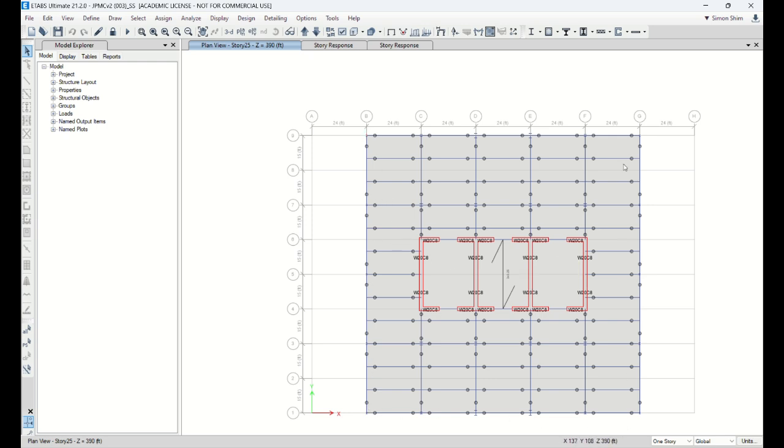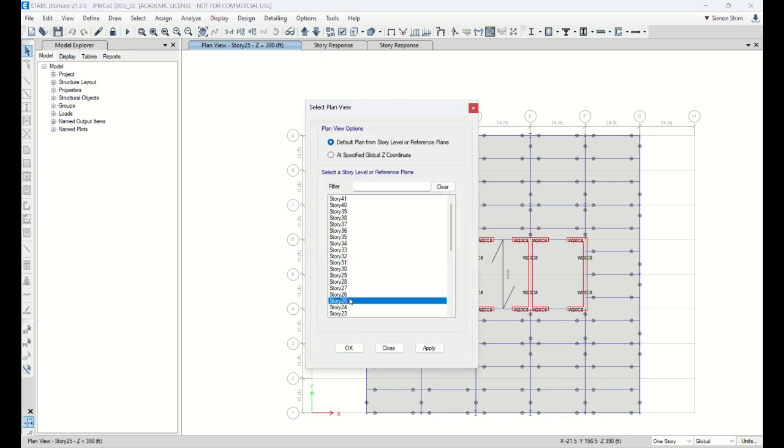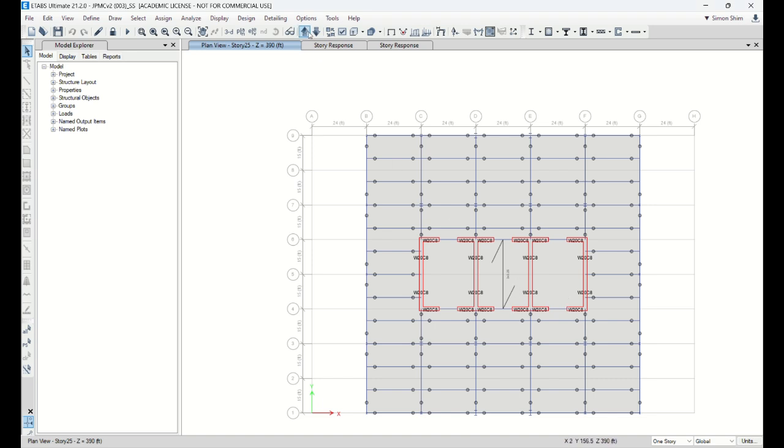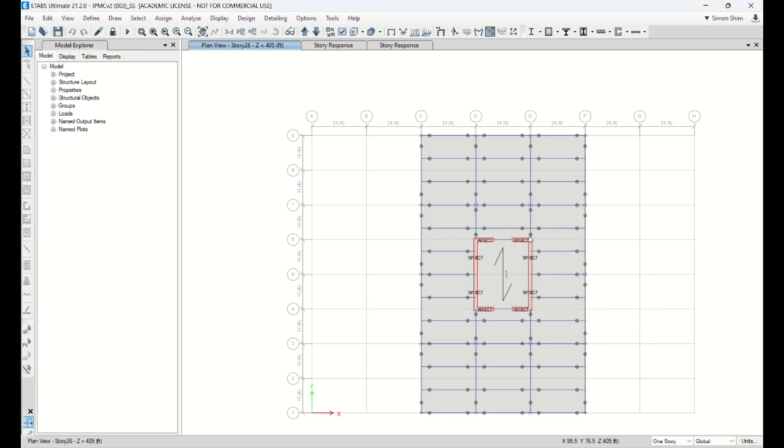So when you look at this building, I think the base is more square. So total wind blowing in x direction, y direction, they are very close, right? But when you look at the core wall layout, obviously the core wall is a longer, rectangular shape. So stiffness wise, I think the x direction is stiffer than y, right? But when we go up, I think the wall actually drops. So the core wall is basically 30 by 24.